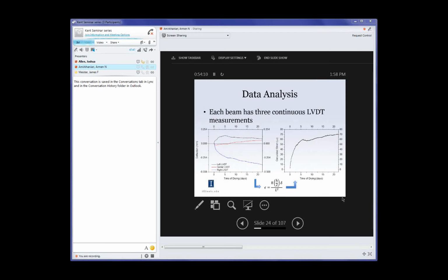So why didn't you just use unloaded, no-spring LVDTs? Because if the beam changed direction or shifted, you put one in here, one in here, you measure this one over there, this one over there. But if you have a free-core LVDT and then the beam moves away from it, you stop getting readings from this one. The spring load lets us get readings regardless of where the beam moves.